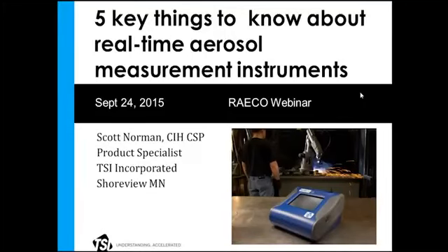Just to put in perspective, just to start out, how do you measure aerosols, and why do we measure this way? I asked that to a group of hygienists, and they just kind of sat there, right after lunch. It was the carbo loading kicking in. So we measure aerosols gravimetrically, usually, because that's what our metrics are based on. Most of our aerosol metrics are mass. It's milligrams per cubic meter. It's micrograms per cubic meter for silica, for welding fume, for any other aerosol dust you can think of. So that's why traditionally we've done a lot of gravimetric measuring, I think.